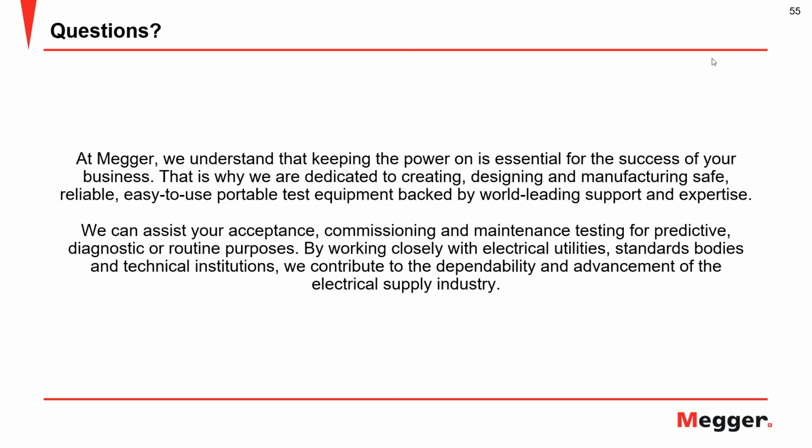So from today's perspective, the go-to cable test is an AC, and in this case VLF test, for the benefit of having small equipment. And also obviously the partial discharge test is done with an AC test with a near line frequency AC wave shape.